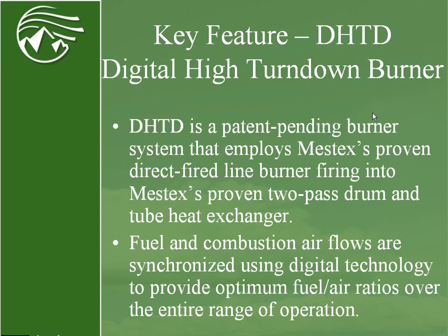The DHTD burner is actually a digital high turn down burner, patent pending through Mestek, the original company, and it's a drum and pass tube heat exchanger. It's a two-pass drum and tube heat exchanger, which is actually a lot more efficient than your standard clamshell heat exchanger. And basically, the fuel and combustion airflows are synchronized using digital technology.